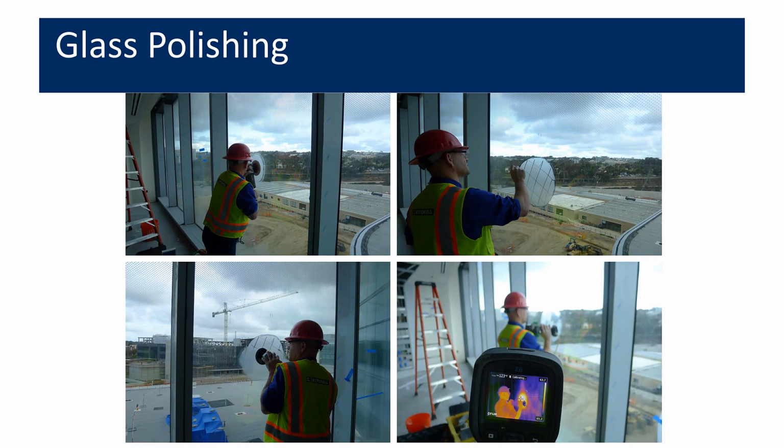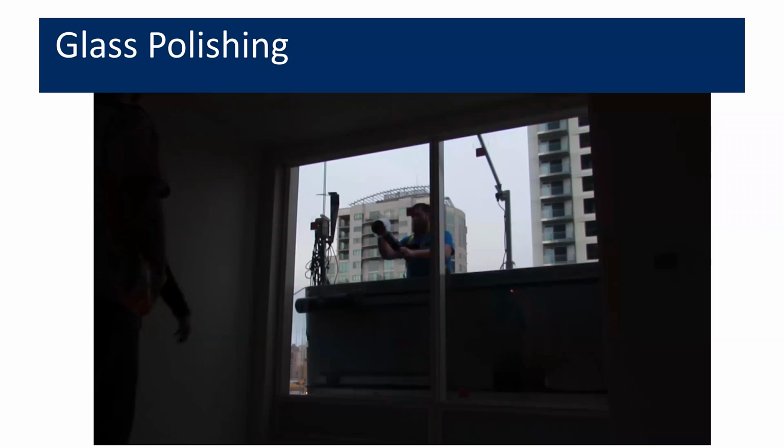And in this process, you might get concerned that you're heating the glass to high temperatures, and specifically if it's heat-treated glass to begin with. However, in measuring those temperatures using an infrared camera, we've seldom found temperatures rising above about 300 degrees, which is relatively benign for the glass. But let's take a look at a typical cleaning process here.